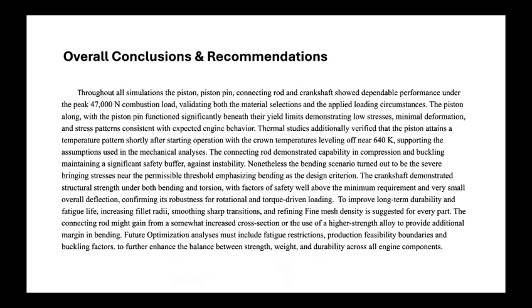To extend durability and improve fatigue life, we recommend increasing fillet radii, refining mesh density in high-stress regions, and smoothing sharp transitions across all parts. In the future, incorporating fatigue modeling, manufacturing limits, and additional optimization variables will help further improve the balance between weight, strength, and durability. Thank you for listening.